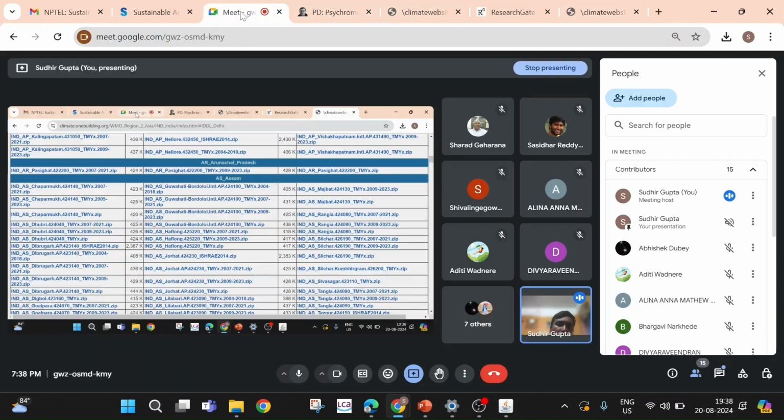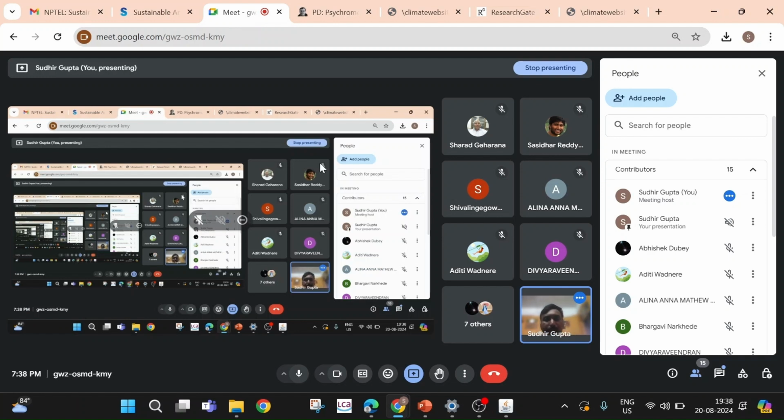So what I wanted to say now, I think I am clear: if through Climate Consultant you are downloading the weather data files and it is not there for your city or your area, then with the help of the One Building organization site, you can download the EPW files and do your analysis. Is that clear? Yes, sir. Okay, so let's move to the question again.